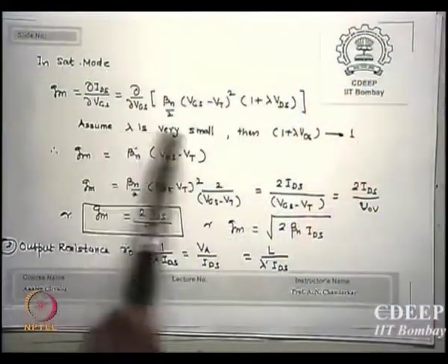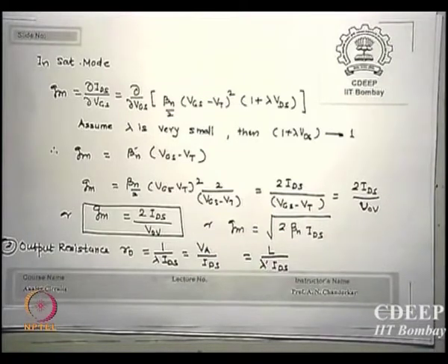So for MOS circuits, unless stated otherwise, we will assume lambda to be 0, in which cases? When I write currents. But when I write R0, I will not make lambda 0. R0 would then be infinite, is that correct? Lambda 0 means slope is 0, which means resistance is infinite. But that is never infinite, and therefore calculation of R0 will definitely involve a value of lambda. Otherwise, in the normal current equation, if you neglect lambda, nothing much worse will happen in actual analysis.